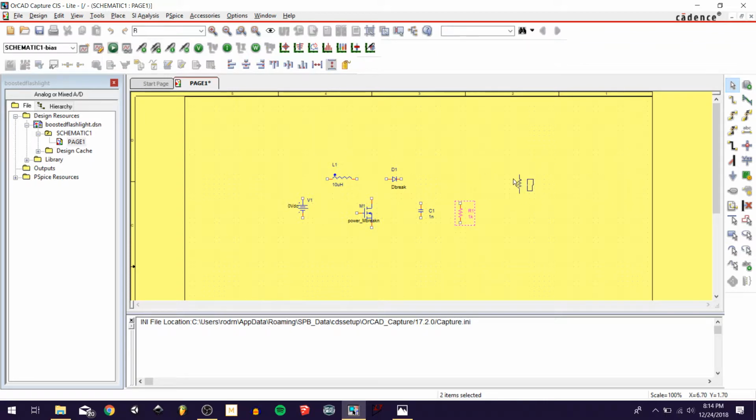And so I again place down that resistor just so I have a load for my boost circuit to work on, and I'm gonna set it up so it draws about the same amount of current. Well, eventually I'll set it up so it draws about the same amount of current as the LEDs will. So next I'm gonna go up here. Sorry. I'm gonna put my grounds down now.